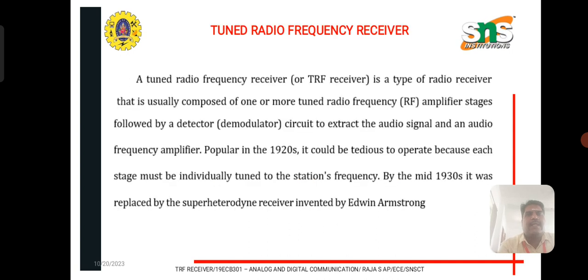So that is what we discussed. A tuned radio frequency receiver is a type of radio receiver that is usually composed of one or more tuned radio frequency amplifier stages followed by a detector circuit to extract the audio signal and an audio frequency amplifier.